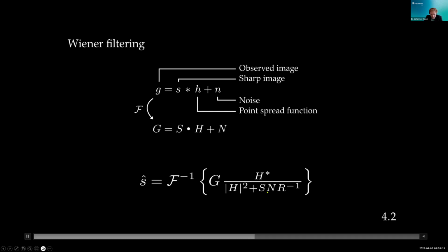This is the so-called signal to noise ratio, which is a very crucial component of the Wiener filter. It basically tells us, or should tell us, for every spatial frequency, whether our signal has the most energy in our observation for that spatial frequency, or whether it is the noise. And if we have a low signal to noise ratio, then we should better not try to reconstruct the image at that spatial frequency, because that will enhance any noise that is present in our observation.